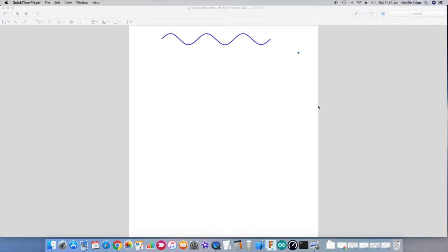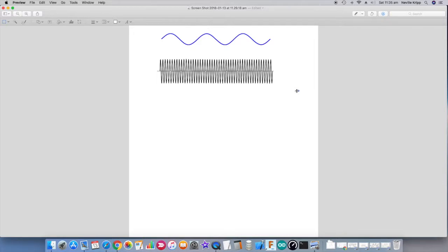So let's consider we have an audio signal. So it could be the microphone, it could be music or something like that at a radio station. And what we want to do is modulate a carrier wave. So the carrier wave is simply going to be a sine wave at the frequency that the radio station operates at. So if the radio station is 100 kilohertz on the dial, then that carrier wave frequency will be 100 kilohertz.